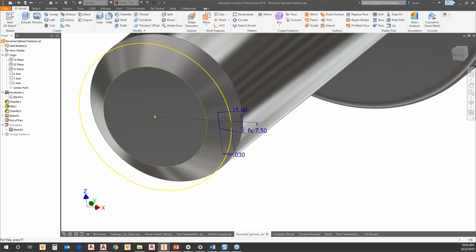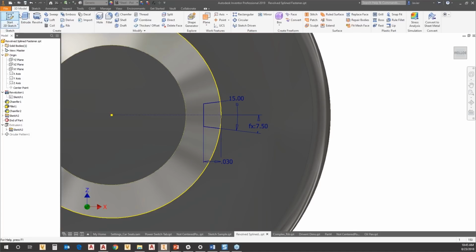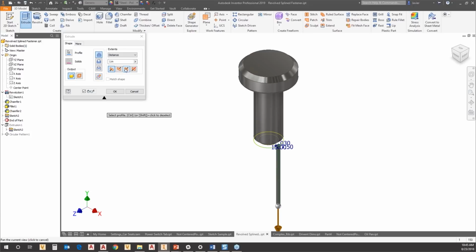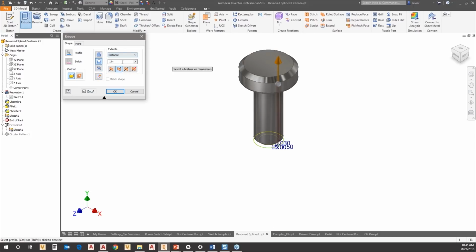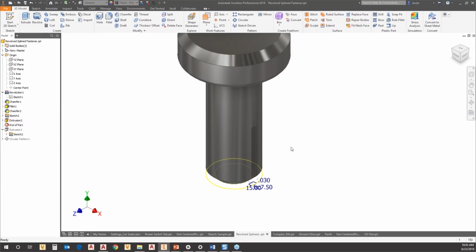make sure I did this. All right, simple click here. There wasn't a whole lot to choose between. There's really just two boundaries as opposed to three or four or five, and I can start to extrude and cut that. All right, so we'll just change the direction there, cut it up this way, and maybe just extrude it a half inch. Okay, so the formatting of that helped.